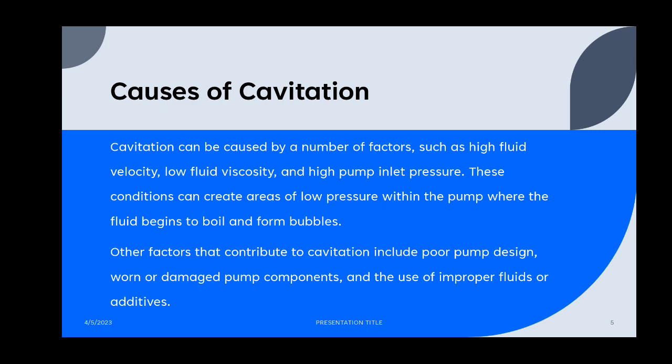Other factors that contribute to cavitation include poor pump design, worn or damaged pump components, and the use of improper fluids or additives. So these are the causes of cavitation.